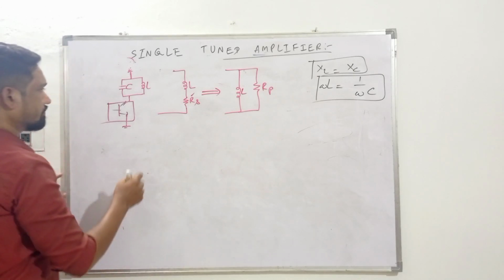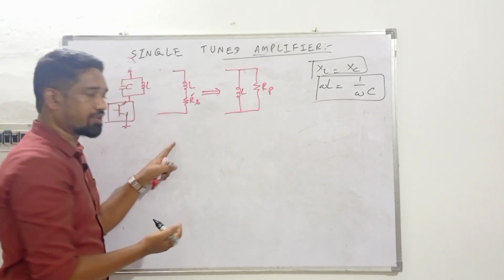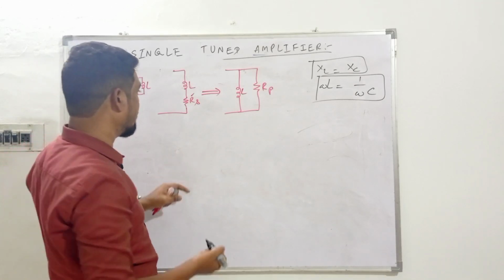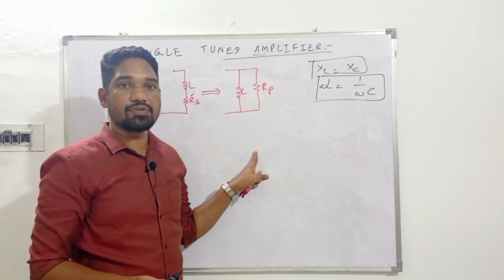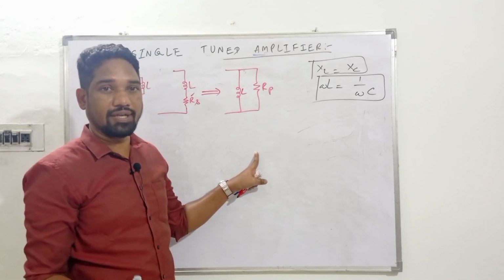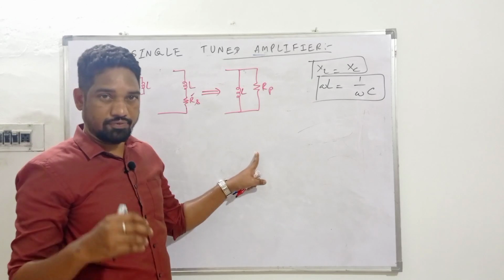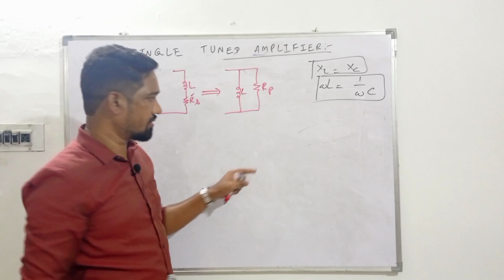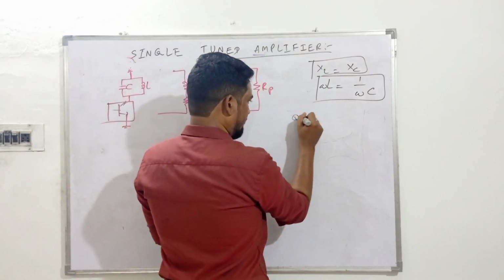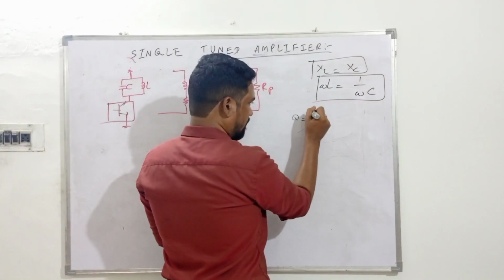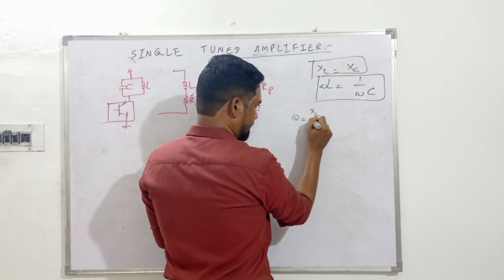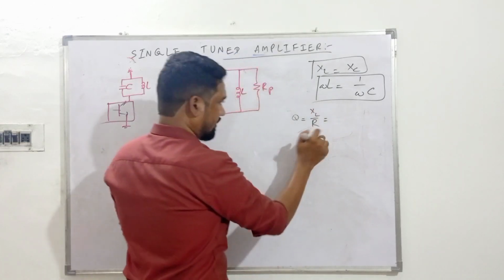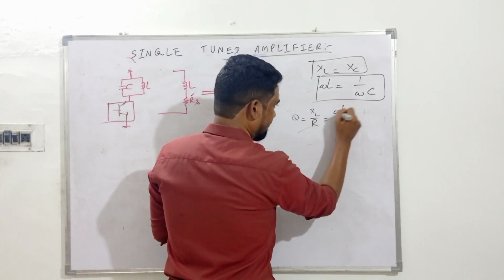Okay, so what is the expression for quality factor? When it comes to inductors and capacitors, there is a need to consider the Q value, the quality factor, which is the index for the performance of the capacitors and inductors, right? So its general expression for Q is, what is that? Reactance offered by the inductor, XL, by the resistance, XL by R. And XL is omega L, so Q is omega L by R.